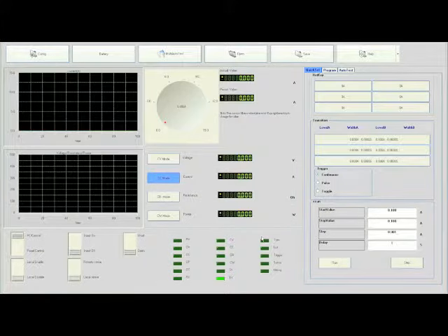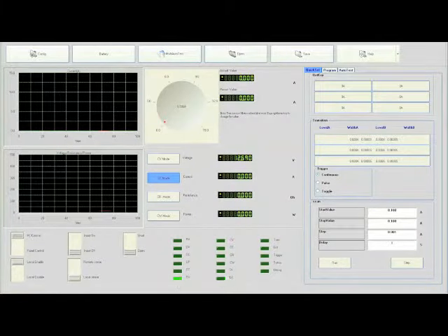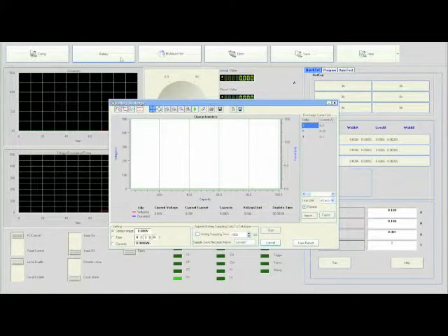If settings are configured correctly, the software will immediately detect the instrument and connect. The RX and TX light indicators at the bottom indicate communication between the load and the computer. Now click on the battery button at the top to enter the software battery test function.